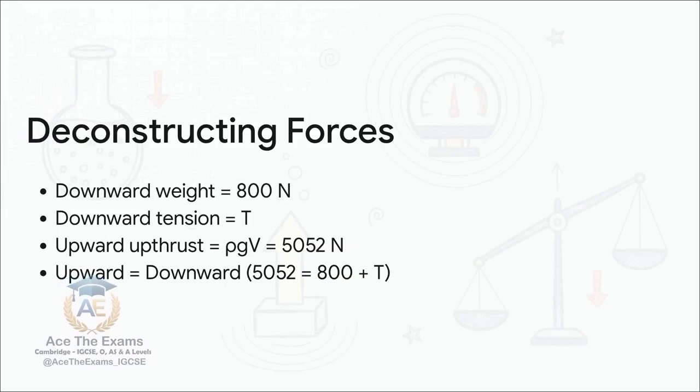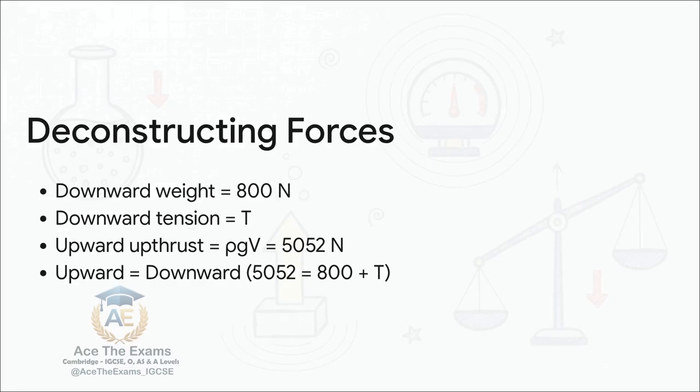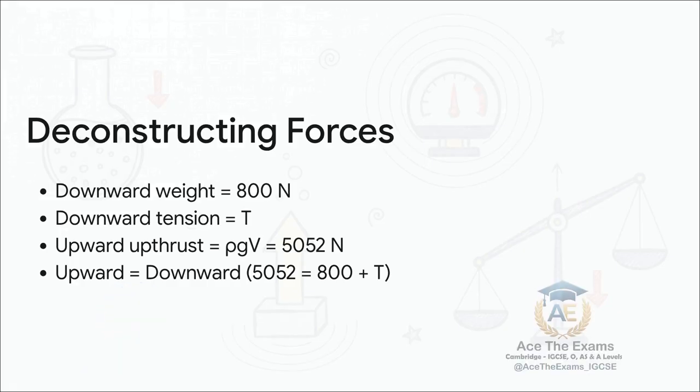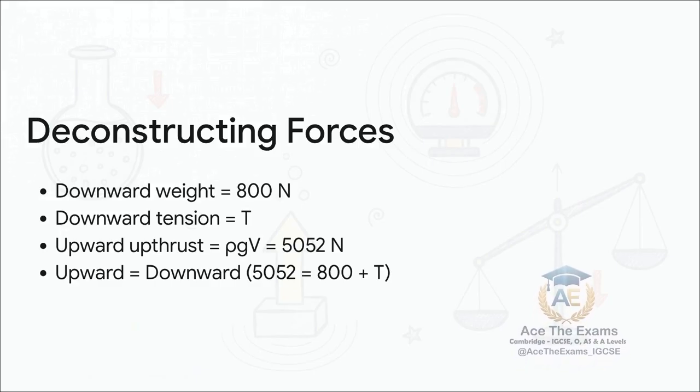Now, what's pushing up? That would be our upthrust from the displaced seawater. Grab the formula, rho times g times V. That's 1030 for the seawater, times 9.81, times 0.500 for the volume. That spits out a massive upward force of 5,052 newtons.